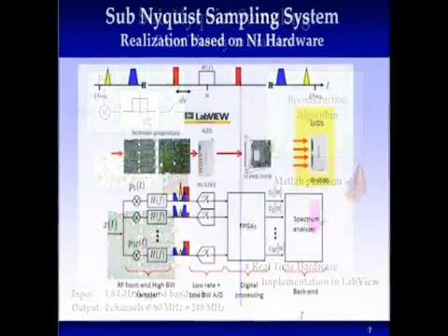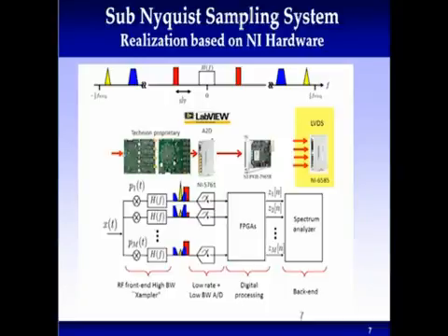And then we transferred the theoretical approach into practice by constructing the modulated wideband converter, MWC, and implementing the reconstruction system. Here we can see the general overview of the implementation of our algorithm based on National Instruments hardware and development software LabVIEW. The first part, our smart sampling cards, followed by a low-rate digitizer, and then 3 FPGA cards for signal reconstruction.